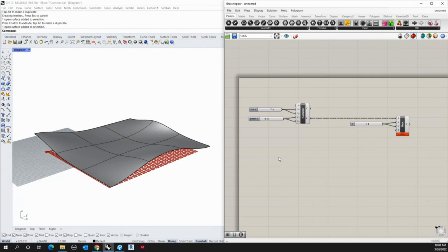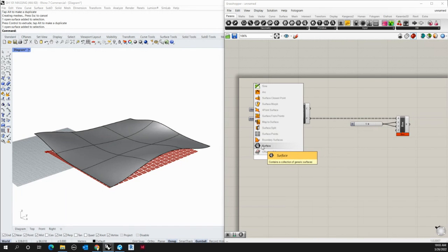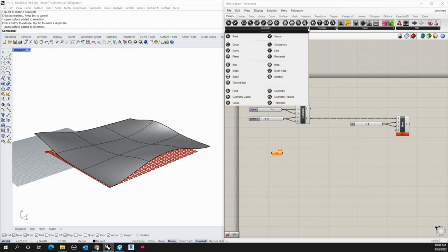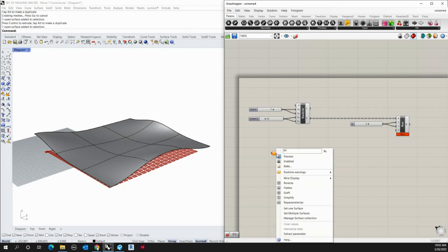So I'll do the little trick that Holly showed earlier, creating a surface, but creating the surface tool with the little black hexagon, which is just a container to reference things from Grasshopper. If you want to find it in the menu, it's these guys. At the first tab and the first panel, these are all your containers, whether they're surfaces, etc. And then I right click on it.